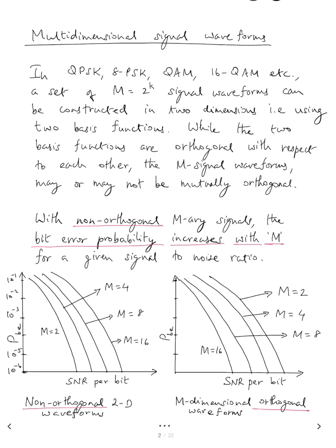The same pulses, if we transmit with m equal to 4, then each duration of t seconds would represent 2 bits of information, and that would mean that if 10 pulses are transmitted, that would be 2 into 10, 20 bits per second. So in order to increase the bit rate, we have to increase m.